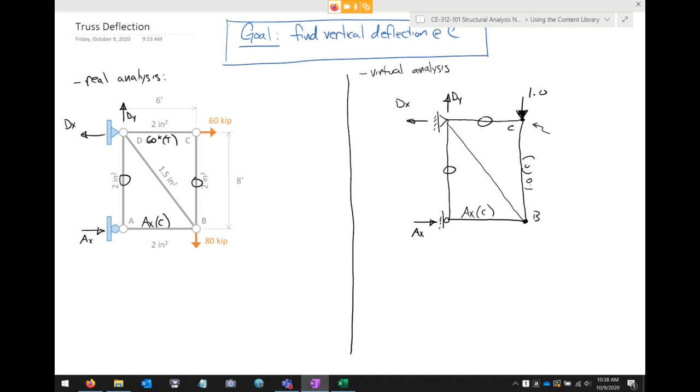So you can figure a lot out without even breaking out the pencil and paper and doing any structural analysis. In fact, let's take a look at this virtual structure. Take a look at the joint analysis on joint D. Those are zero force members, the horizontal and the vertical coming into joint D. So I propose then that this is just the square root of dx squared plus dy squared. Now, can somebody help me out? Is that going to be tension or compression? What do you think?